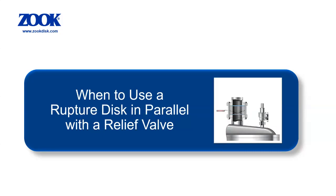Rupture discs can also be used in parallel with a relief valve. A relatively small relief valve can handle any low-level pressure relief requirements, with the rupture disc providing additional capacity for extreme requirements, for example, a fire case scenario. This saves the high cost of installing a large relief valve, which is not required for most relief cases.